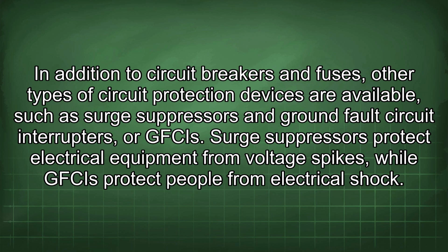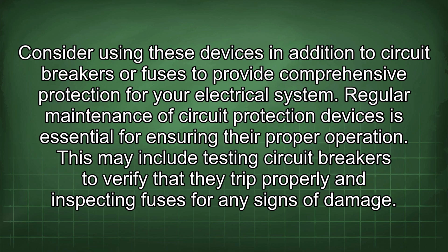Surge suppressors protect electrical equipment from voltage spikes, while GFCIs protect people from electrical shock. Consider using these devices in addition to circuit breakers or fuses to provide comprehensive protection for your electrical system. Regular maintenance of circuit protection devices is essential for ensuring their proper operation. This may include testing circuit breakers to verify that they trip properly and inspecting fuses for any signs of damage.